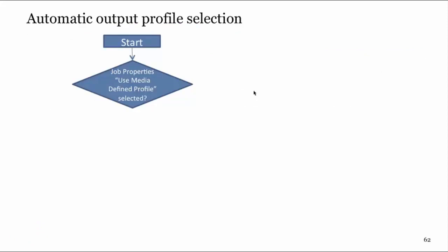If I specifically pick in Job Profiles an output profile, like the Fiery demo profile that we showed you earlier on the flowchart, then you're going to use that profile just for this job. This is absolutely the worst way to configure your DFE. If you're manually picking a profile for each job each time you print, there's a high probability that you or one operator in the shop is going to pick the wrong profile one day, or that you're going to pick different output profiles on the first shift compared with on the second shift.